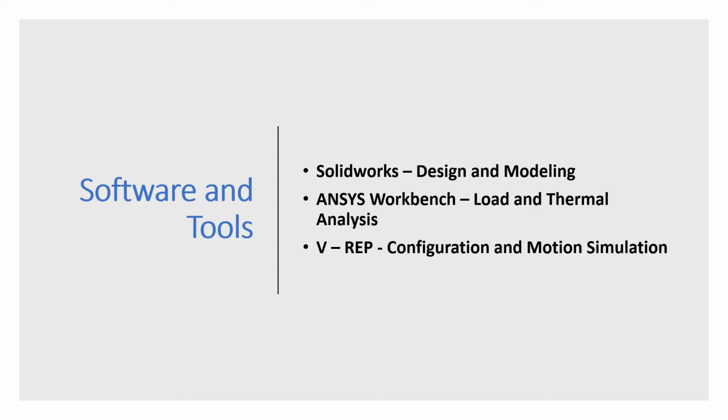ANSYS Workbench is generally a FEA, that is a finite element analysis tool, which is usually used in the engineering field for simulation purposes. We need a CAD model to proceed with ANSYS. So the CAD model is designed on SolidWorks and is imported into the ANSYS Workbench software. The model is then meshed, and then the analysis is